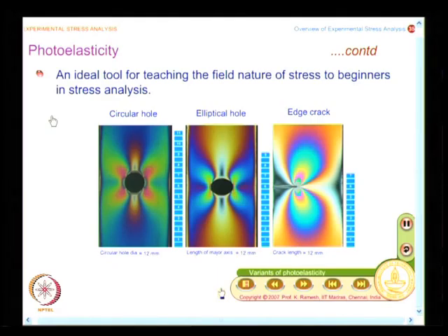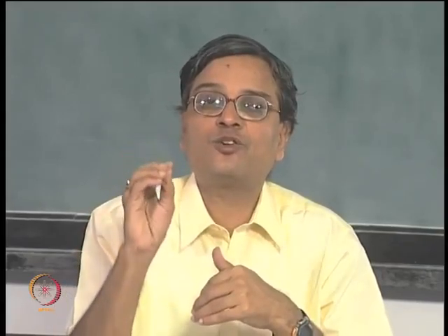And here I must tell you, stress concentration you all know right now. I have a plate with a circular hole, I have a plate with an elliptical hole, and I have a plate with a crack. Now anybody in engineering will know what stress concentration is, but if you look at the history, mathematicians and stress analysts had an acrimonious debate. Mathematicians used to say an infinite plate with a small hole is equivalent to a plate without a hole, and only with experimental judgment and other aspects they were able to convince that a whole lot of things happen the moment I introduce a stress concentration.